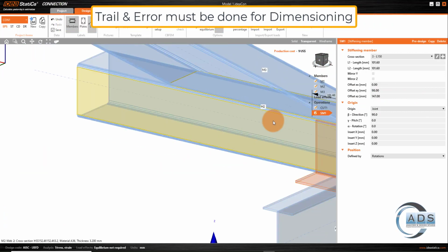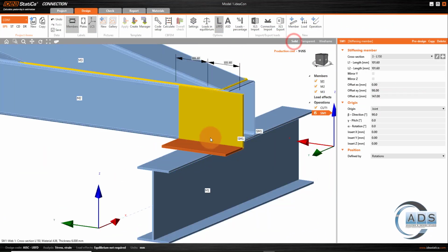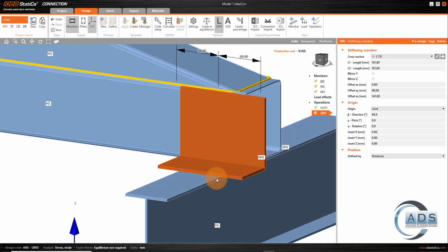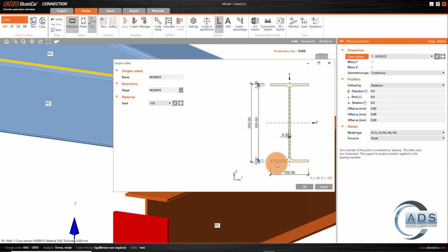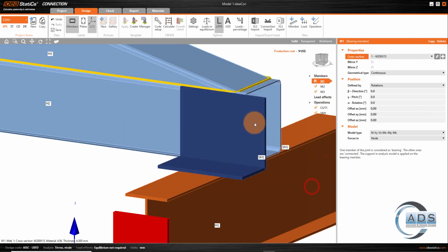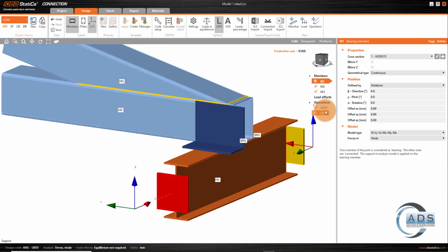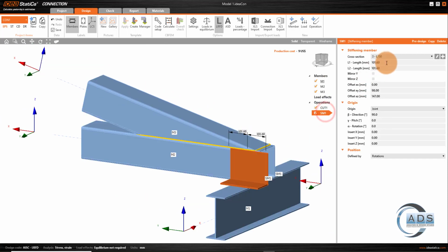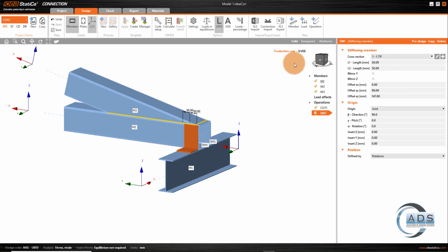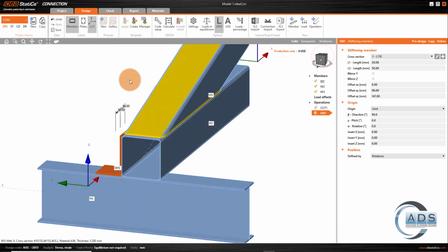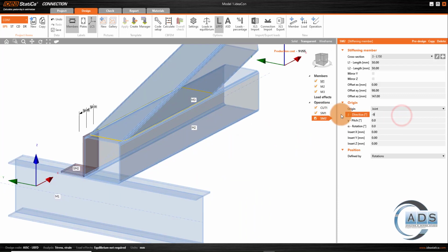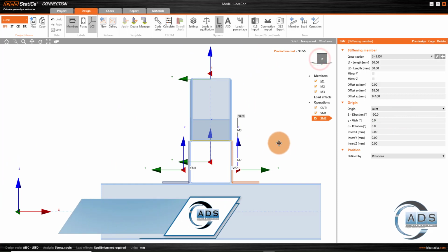Now we have to set its length. Its length should be equal to the flange width of the I girder. So let's check what the flange width is. It's 100. So its length is actually 2 parts. Let L1 be 50 and L2 also be 50. Right, so this is okay. Similarly, we'll copy this stiffening member and give it beta direction as -90. Right, so this is okay.